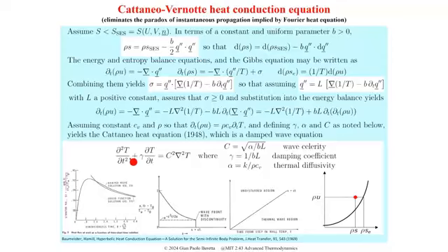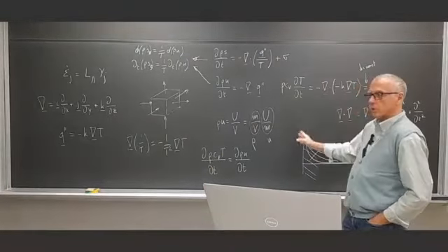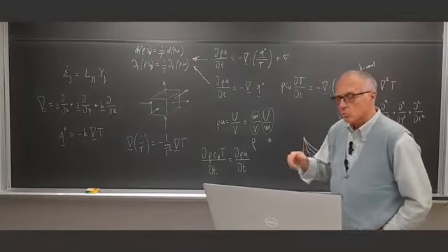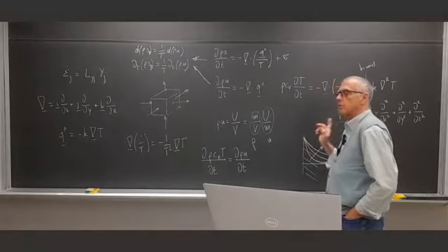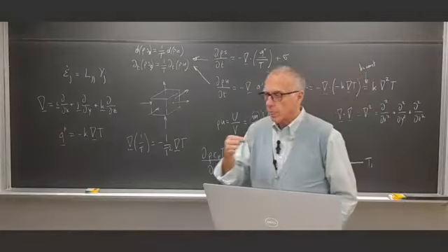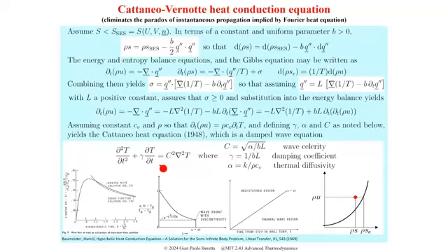And in fact, this equation has been used to represent the early times of this sharp change of temperature problem, or situations in which you change the boundary conditions very quickly, and therefore you need to account for propagation speed, which is this coefficient here becomes now the wave celerity, and the gamma becomes the damping coefficient.